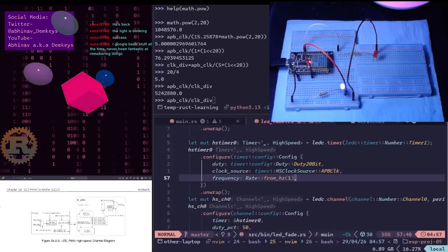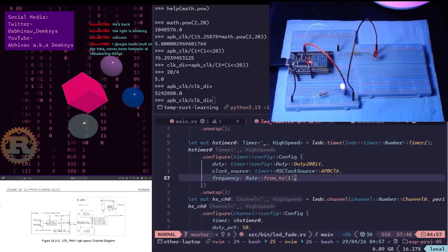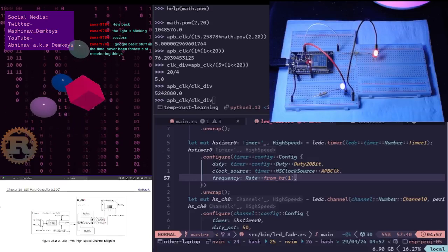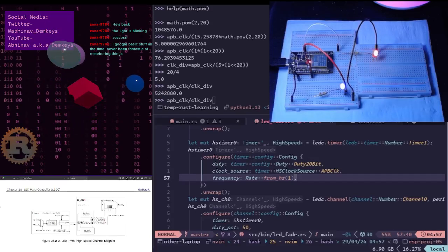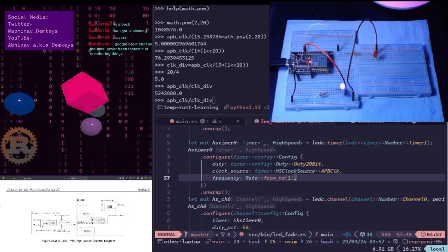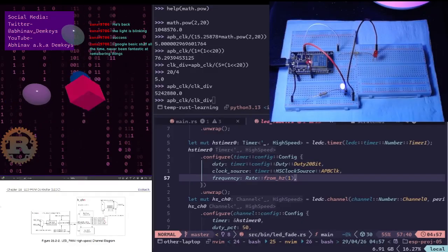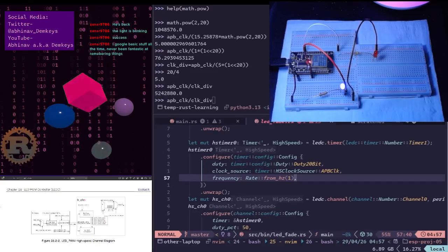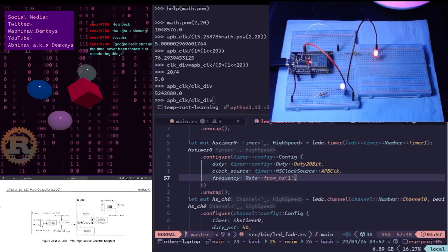This definitely helps. To be precise, the hardware doesn't actually slow down the clock wires. It just chooses which pulses of the high speed clock, or our APB clock, are allowed to count. The pulse swallow mechanism. That's okay.